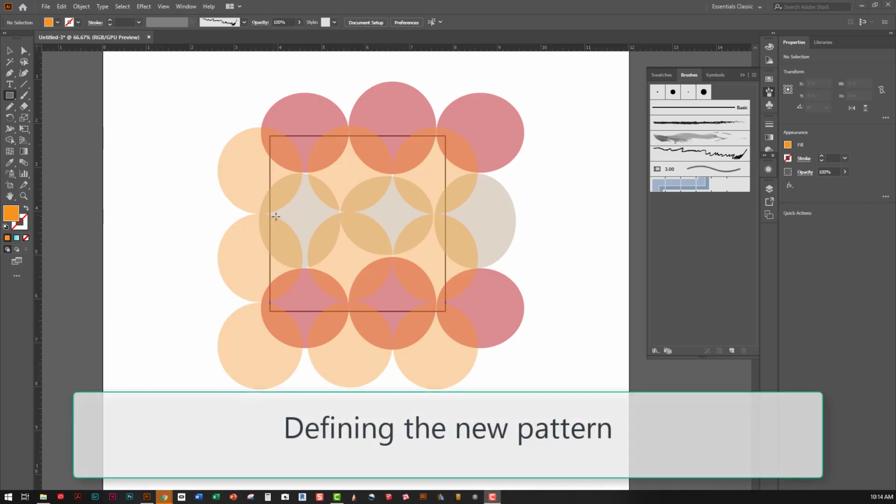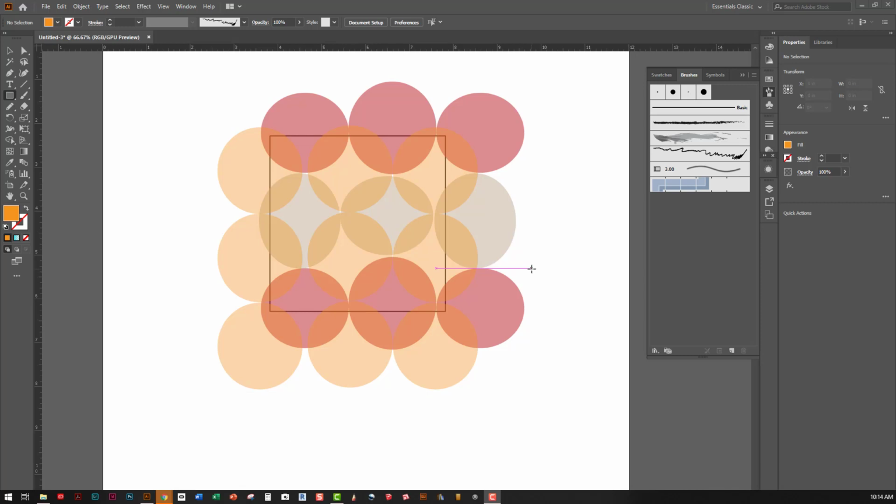One thing to be aware of with all these cool brushes and effects is that the process of creating a pattern within Illustrator will kind of not destroy them, but it turns them into individual strokes and fill patterns. So you will lose the ability to modify them, turn them on and off. So when we create our pattern, we have to be sure to save the original geometry in case we want to come back to it at some point.